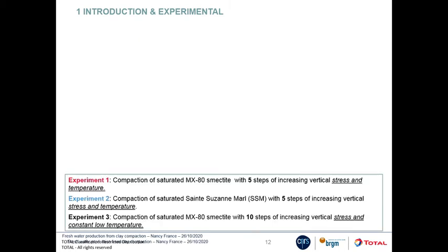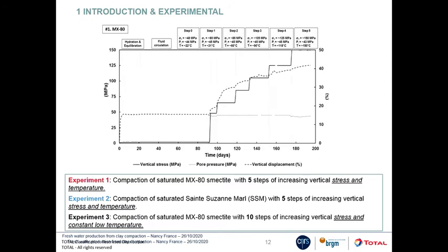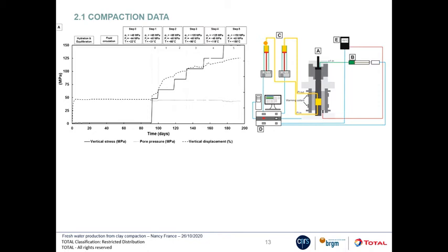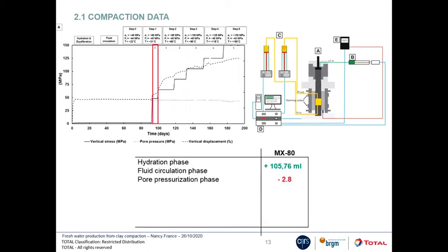We did 3 compaction experiments, which lasted up to around 200 days each. First, we saturated the clay in the cell, slowly, and then compacted it in several steps of increasing vertical stress and temperature, up to 150 megapascal and 150 degrees Celsius, while maintaining the pore fluid pressure as close as possible to 45 megapascal, and continuously monitoring the axial deformation, as well as the volume and composition of water expelled with